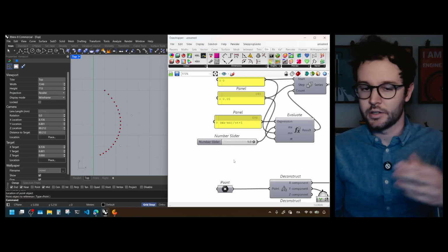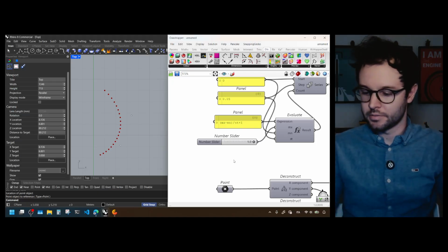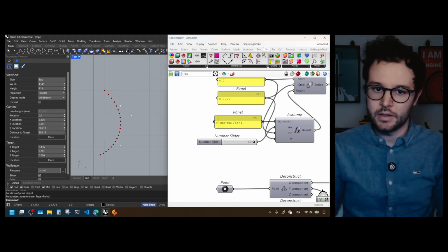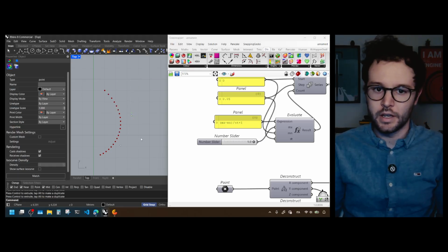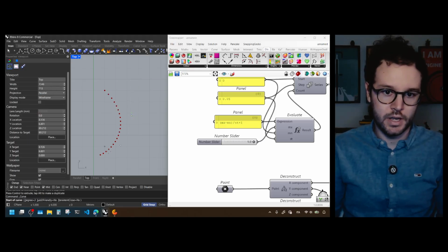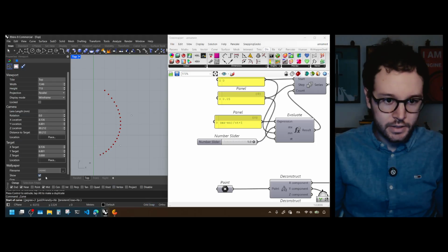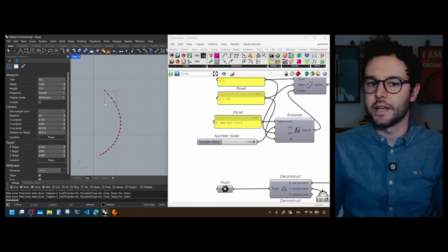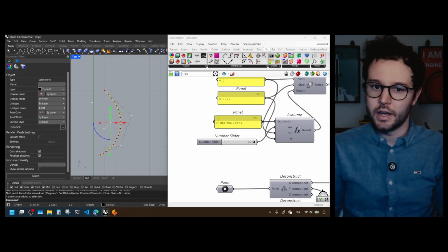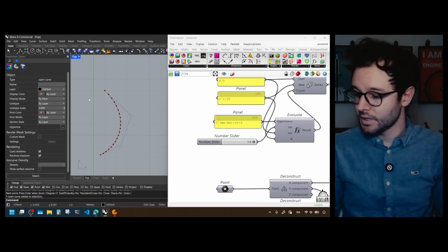And the way these curves work is that we start from the first one, we get to the last one, and these are not points which we pass through, but they still control the position of the line. And indeed, we can also create a cubic with the tools of Rhino directly. Let me snap to points, so we have the same thing. So 1, 2, 3, and 4, and indeed we get exactly the same curve. So we are happy about it.